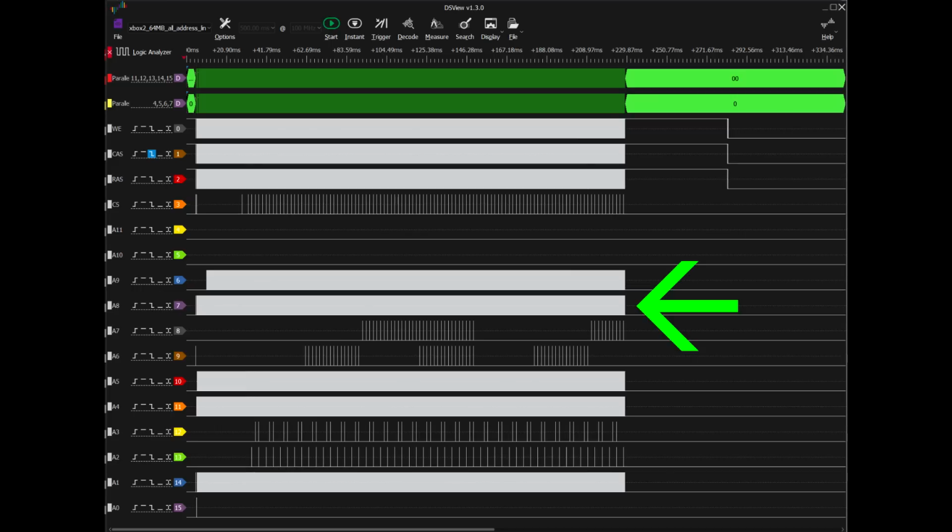It was no longer being used as an AP pin. To me, this seems like a bug in the Xbox hardware, and this meant that I really could not use the system in this configuration because, yeah, without auto precharge, you don't get refreshing, which means you get RAM corruption very rapidly.